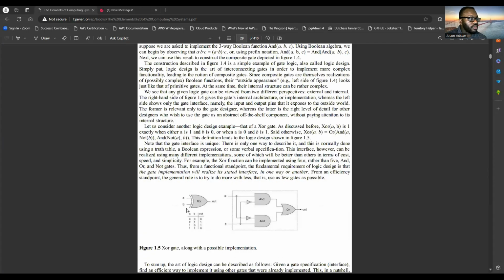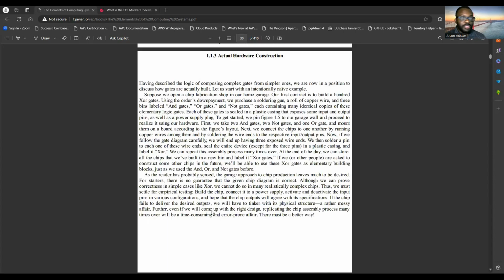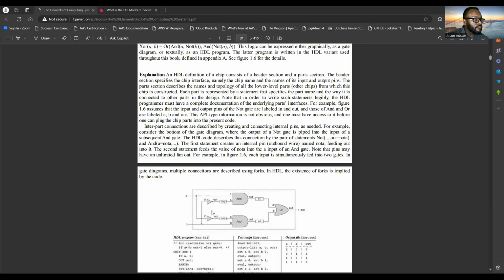Here's an XOR gate, similar, but just a slightly altered symbol. And once again, it's giving you the exclusive OR. So it has to be one or the other, A or B, in order to produce an output of 1. Neither or both will produce an output of 0. These are how the gates work.